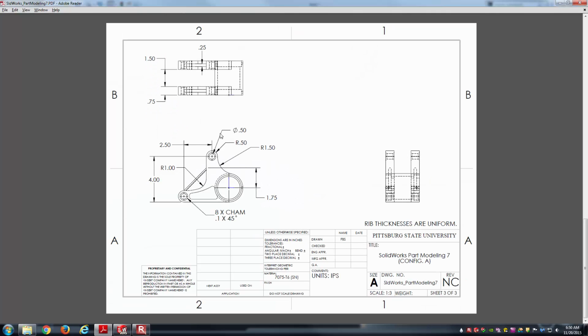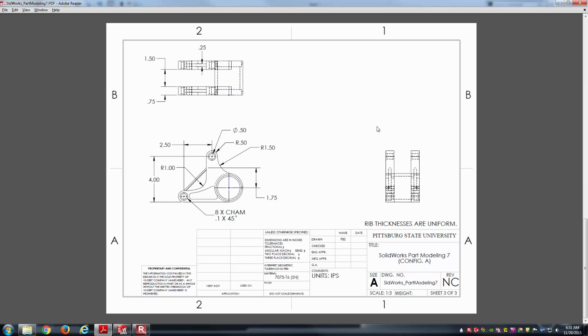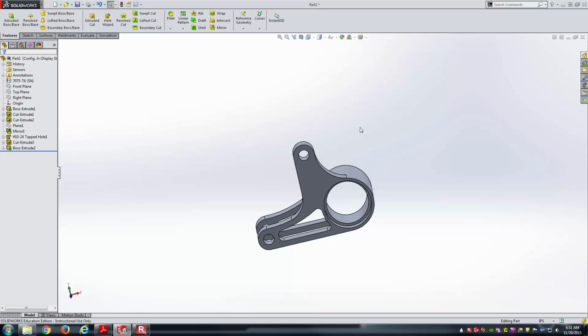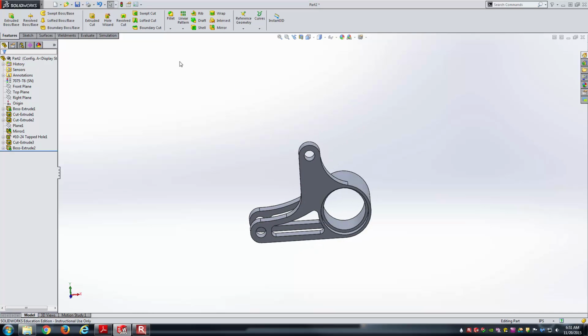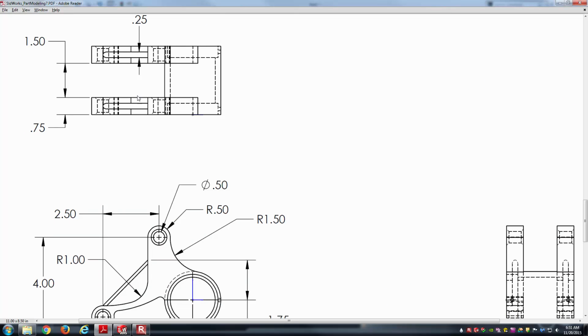The parts as far as the arms and the ribs are identical. So what I'll do is go ahead and apply it on one side, and then I'll mirror everything off to the second side. So let's work on creating the rib first before we mirror. And so there's actually a rib tool right here in SolidWorks, so we'll go ahead and use that. What I notice about the rib is it is on the mid-plane of this small planar area here.